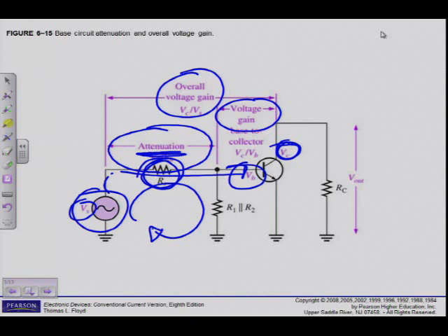But for me that was superfluous. I would have said 0.5 right from the beginning because attenuation is 0.5. So you can approach it that way as well, or you can approach it the way that the book is using it. He says, suppose a source voltage of 10 millivolts input signal and a source resistance combined with a load resistance results in a 2 millivolt output signal. In this case, the attenuation is 10 millivolts divided by 2 millivolts, which is 5. That is, the input signal is reduced by a factor of 5. This can be expressed as a gain of 1 over 5, which is 0.2. All right.